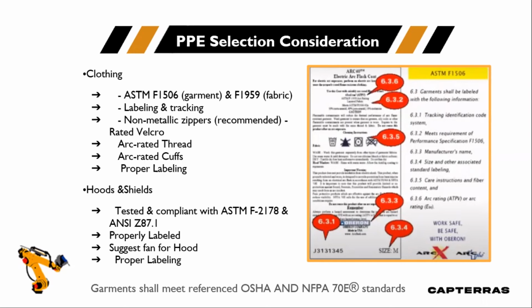These must be tested and compliant with ASTM F2178 and ANSI Z87.1. It should be properly labeled, and finally, it is suggested to have a fan for the hood. Garments should meet reference OSHA and NFPA 70E standards.